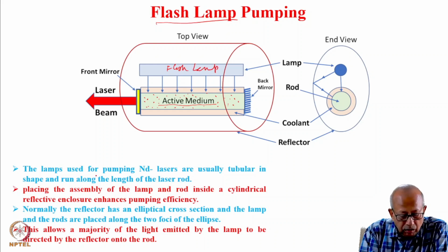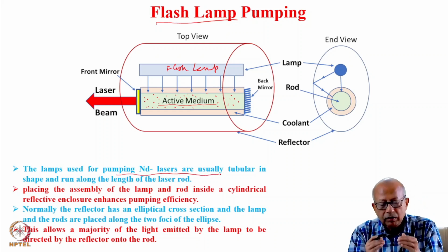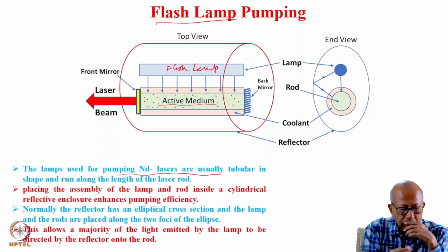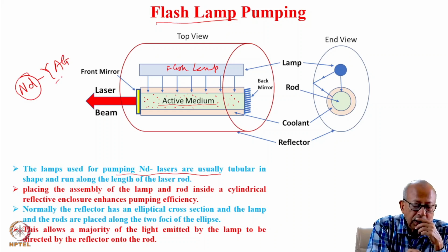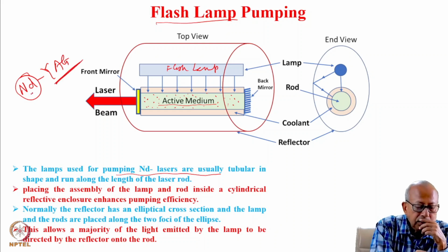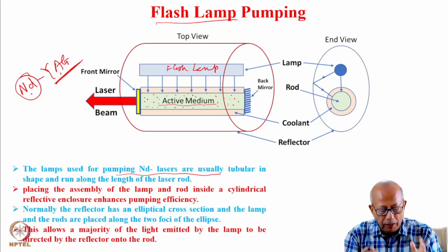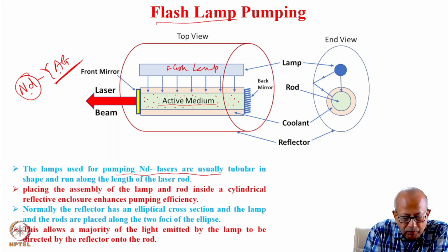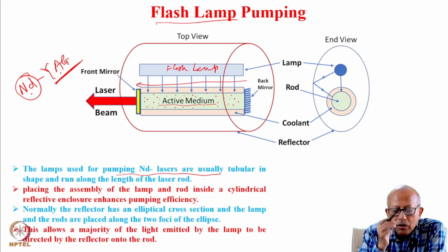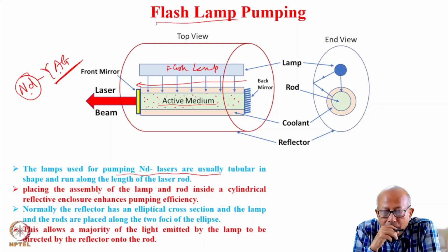The lamps used for pumping Nd:YAG laser, so we are considering the case of neodymium YAG laser. Neodymium is the light emitting atom, YAG is the host, the crystal into which neodymium is doped, embedded. The lamp is usually tubular in shape, and runs along the entire length of the active medium, to increase the efficiency of pumping.